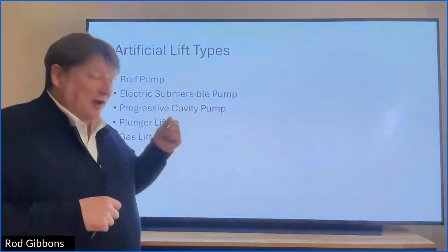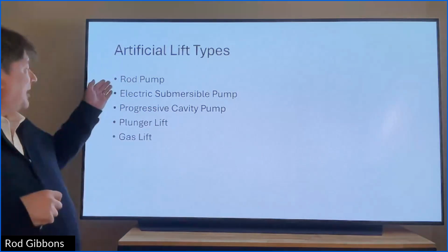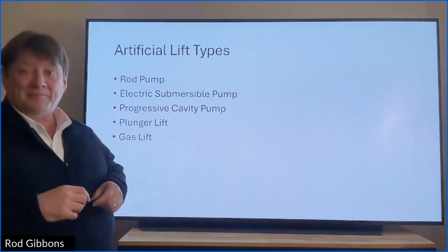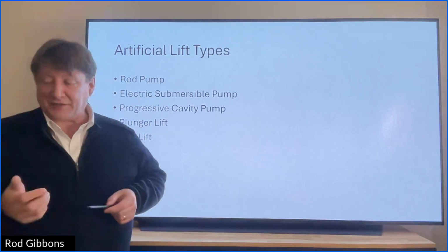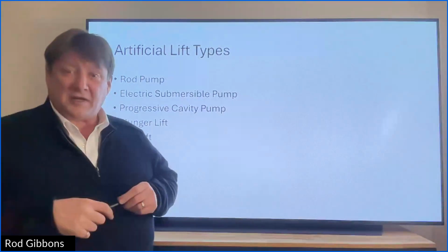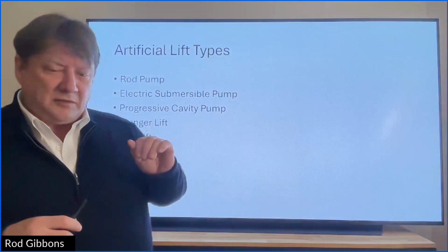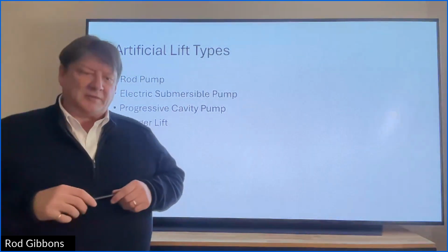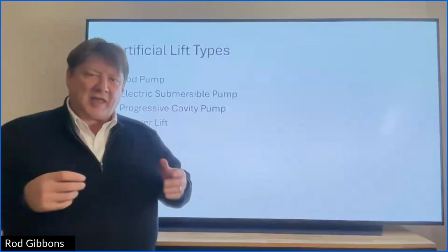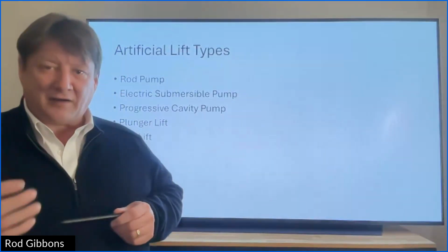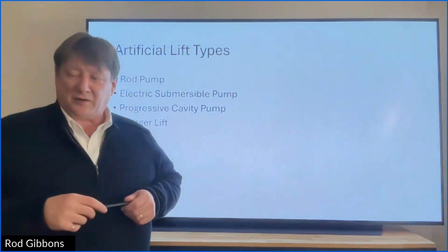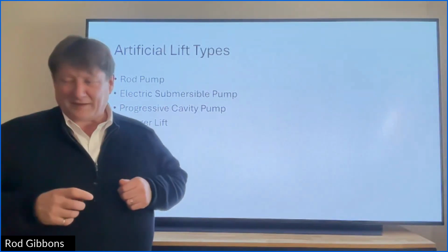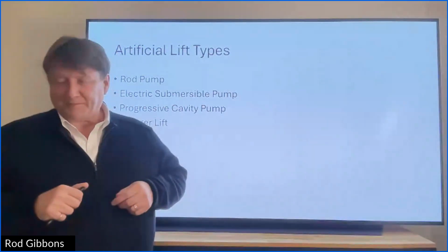On artificial lift, we spent quite some time on rod pumps, and we still have a number of artificial lift types to discuss. But first, there were some questions over some of the rock mechanics and some of the IPR, the inflow performance relationship, and the vertical lift profiles that we went through. So I'm going to spend a little bit of time on that tonight, just reviewing that.